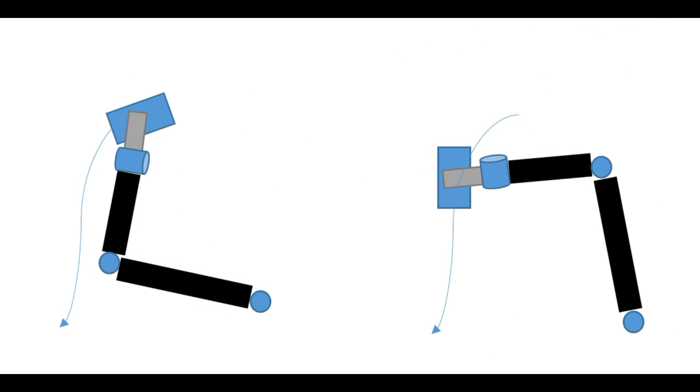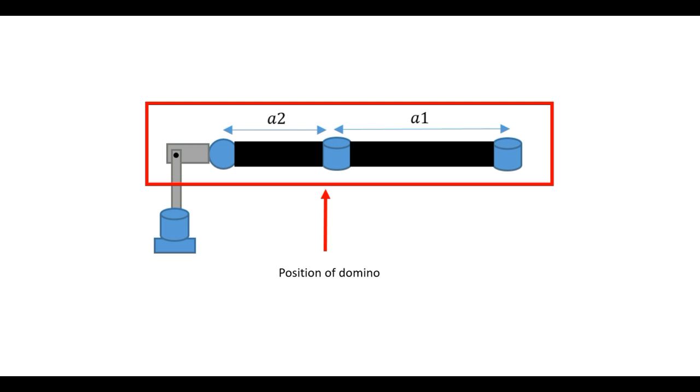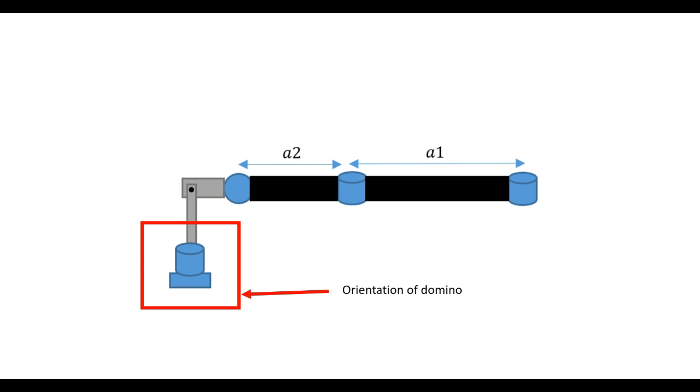Due to the geometric characterization of the arm as described previously, the inverse and forward kinematics problem was solved in two stages: a 2-revolute joint arm and the end effector angular displacement. The first one controls the position of the end effector, and the second one regulates the orientation, which allows us to pick, move, and place dominoes in any position within the workspace.